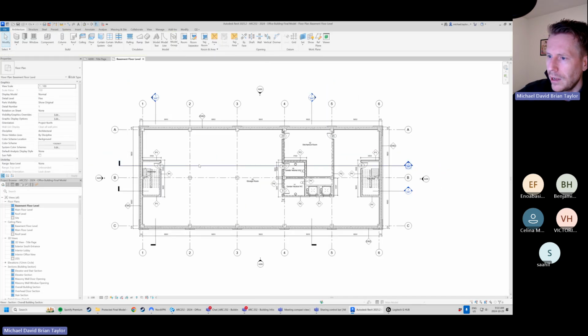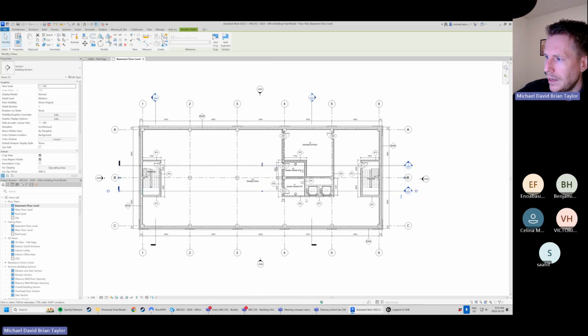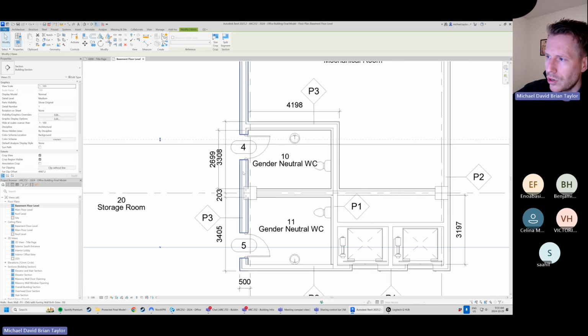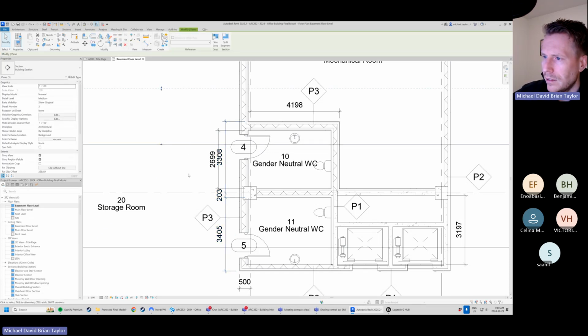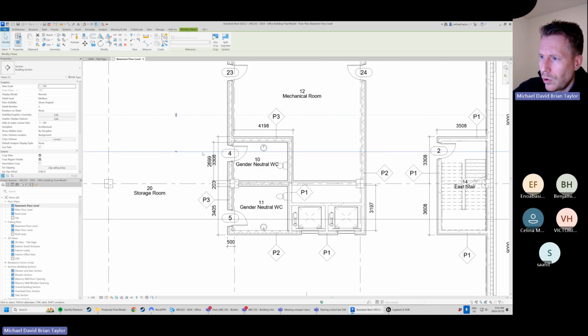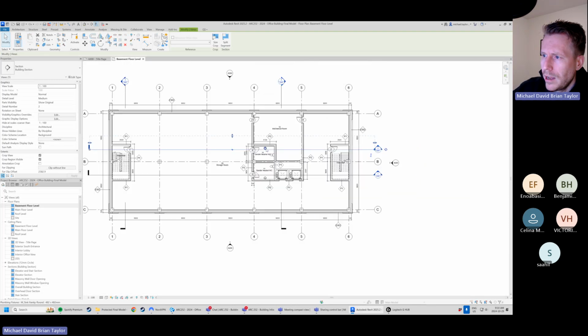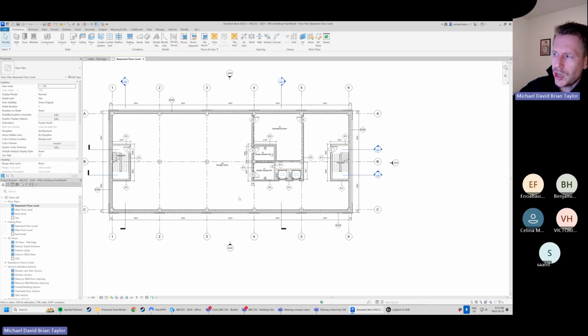But you can see here how oftentimes it can be really confusing for a contractor to figure out where this dimension string is actually being placed if I've got this break line, excuse me, this section marker in here. A handy way to eliminate that is we can just click on the section marker and click that little Harry Potter lightning bolt. Same thing down here, Harry Potter lightning bolt. And now your section is still intact.